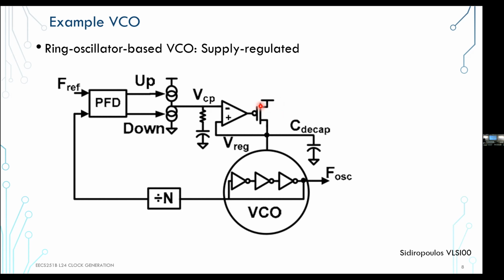The nice thing about that is that the VCO itself, as we've seen, and we'll look at some actual noise transfer functions, is kind of like an integrator, right? So any noise that comes in will basically get integrated. So if it's high frequency noise, it will be rejected a little bit more than the lower frequency noise, right?